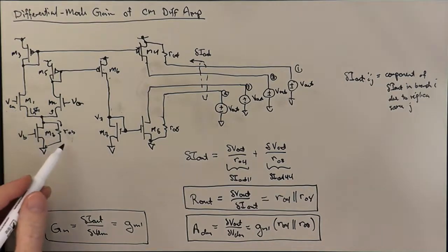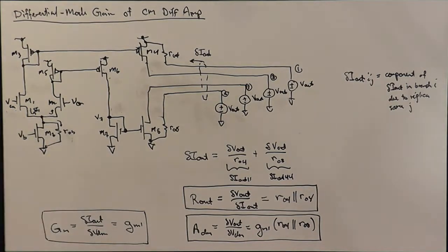Unfortunately, the level of approximation that we're making with that kind of consideration might be somewhere in the range of like a 0.1% approximation to, let's say, a 1% approximation. Let's say if the intrinsic gain is somewhere between 100 and 1,000, that would correspond to the kind of level of approximation that we're making as we chase these current increments around the circuit.